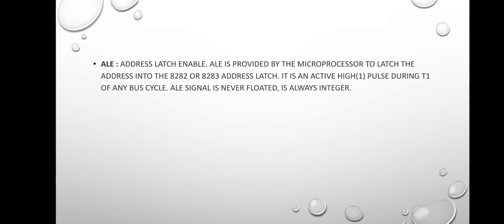ALE is provided by the microprocessor to latch the address into the 8282 or 8283 address latch. It is an active high pin pulsed during T1 of a bus cycle. The ALE signal is never floated and it is always an output.